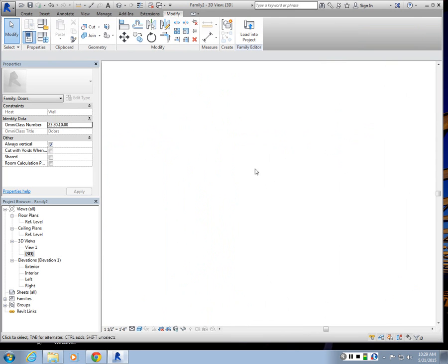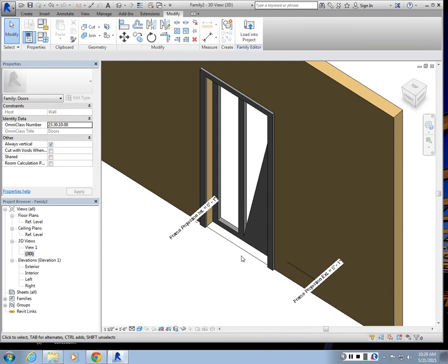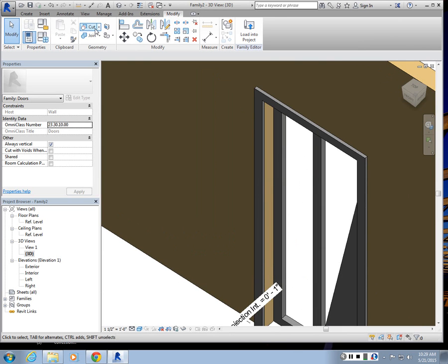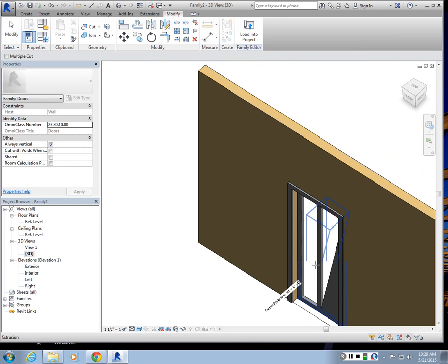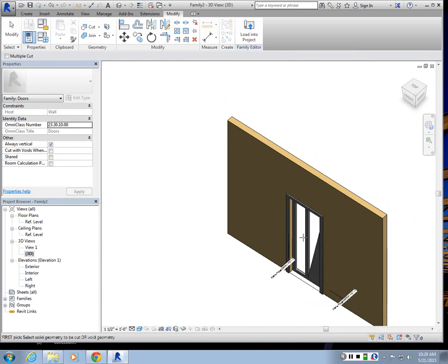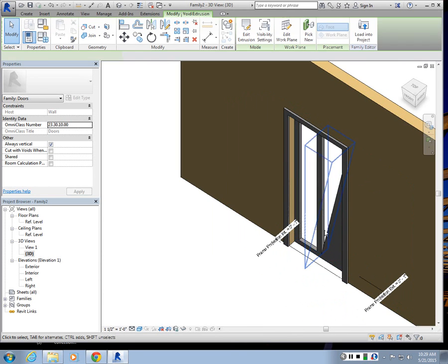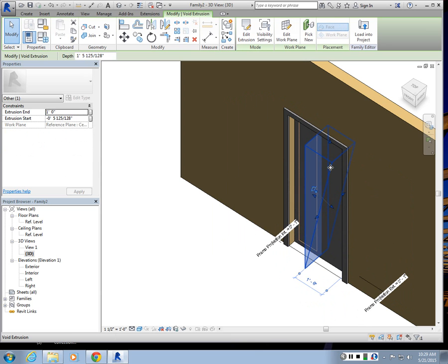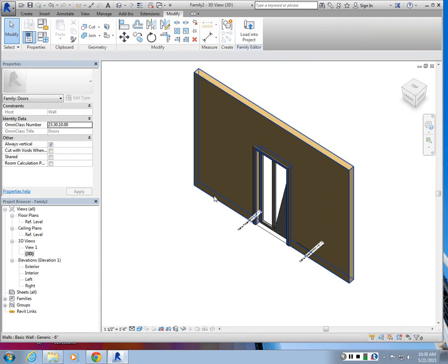So you can model the form, which is a void form, and then you can go to the cut option in geometry. Choose the solid door panel, and then choose the void panel, and then you can cut it so that you create the hole. It should be automatic though. Once you model, you should be able to model the profile of a void extrusion in any viewport, not just in plan. But I guess you can do it this way too.